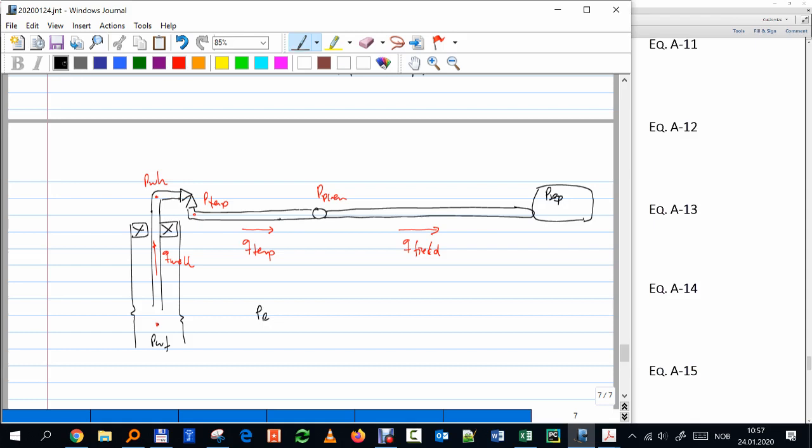Okay, so what I suggest to do is, we don't have this model, right? That's the only part missing in the puzzle. So what I suggest to do simply is take it out of the system, remove it. And I'm going to calculate the energy, that means the pressure which is available here. I have a rate that I want to produce, right? This is 20 million divided by the number of wells. So I impose that rate here, and that rate will lose energy up to here, and then it will have some available energy.